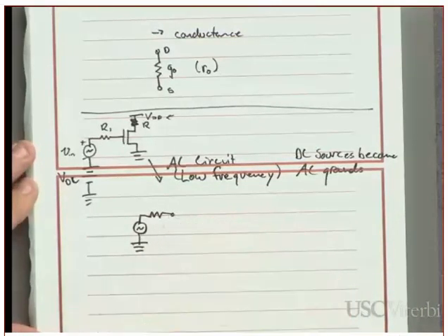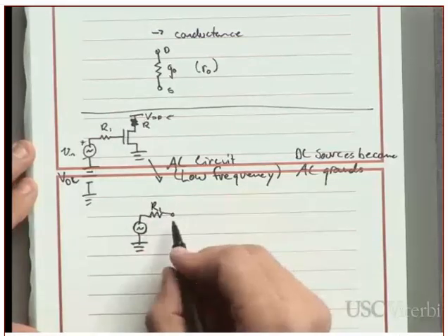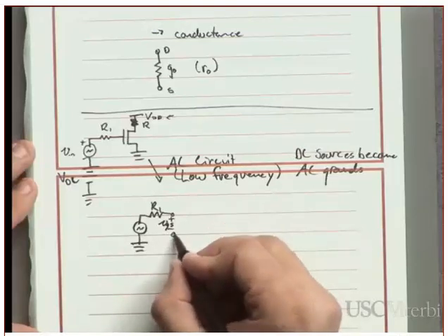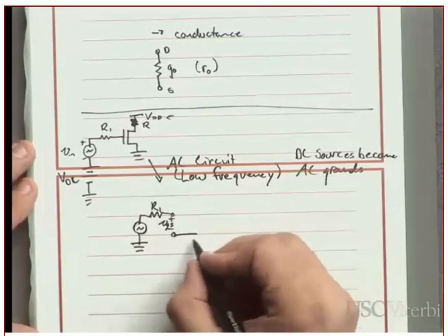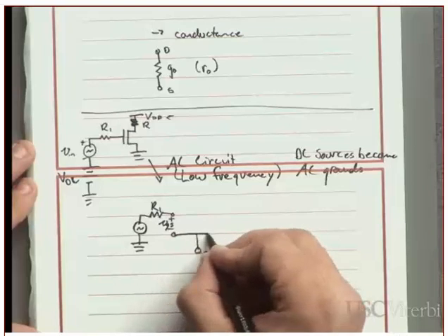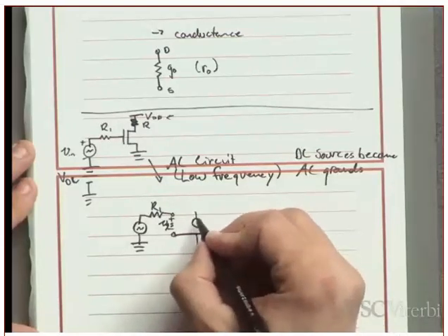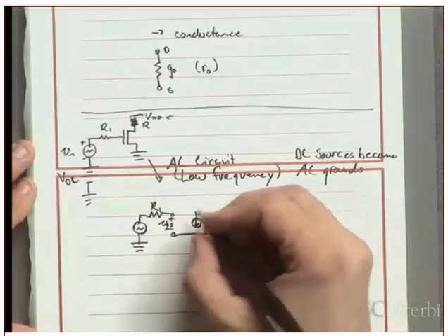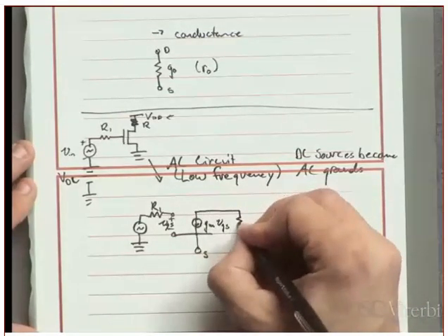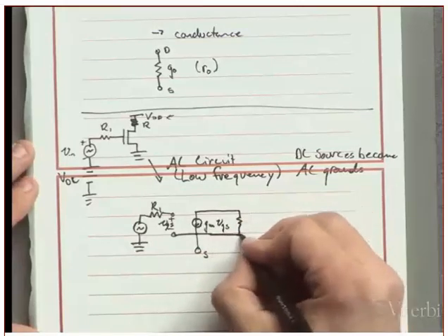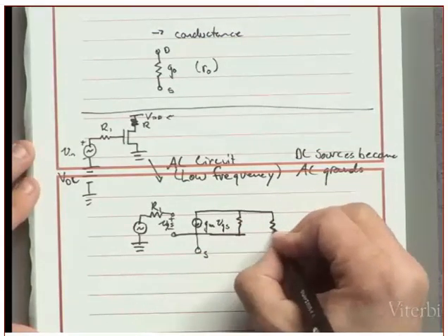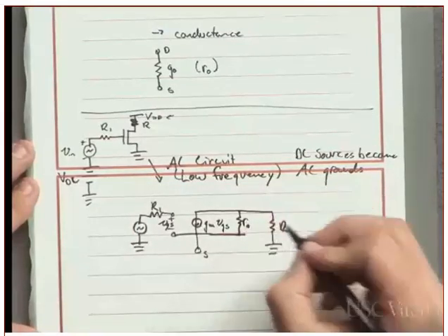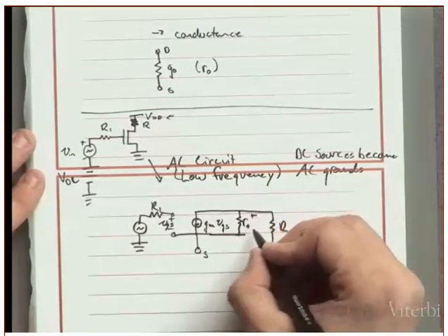the small signal model. So this is the gate of the transistor. And across here I have VGS. So this end is the source. Then I have that generator, GM VGS. And then I'm going to use a resistance, a channel resistance here. And then the resistor up here. So this is R, this is R naught. And my output voltage is right here across R naught.